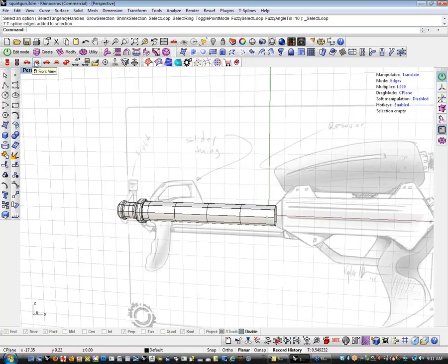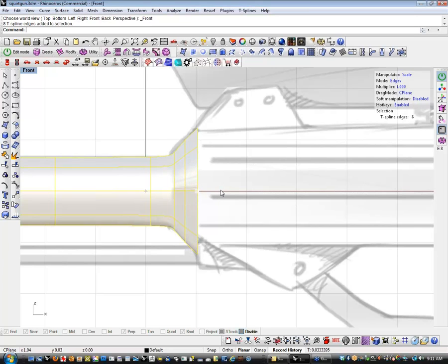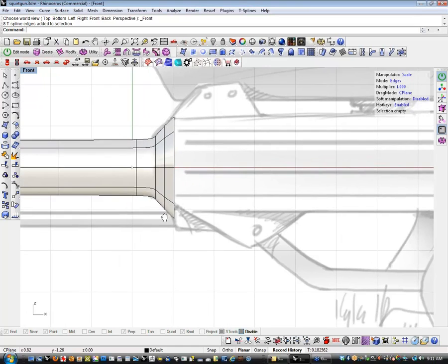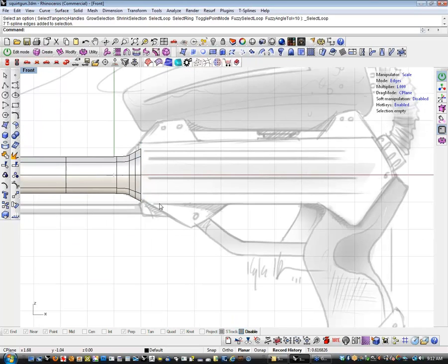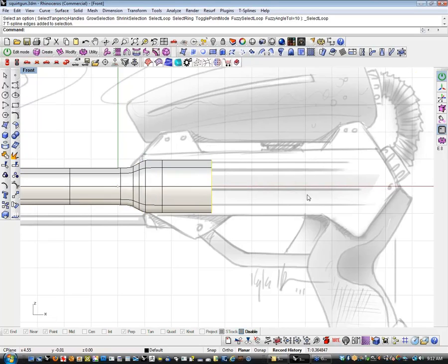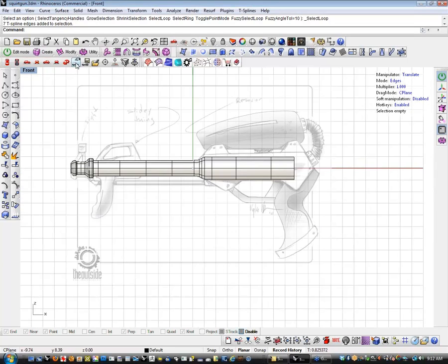Go back here, and I'm going to alt drag out a little bit and scale it to start getting the flare there. Alt drag out again and scale it. And then maybe alt drag out again and scale it one more time. It looks like that's blowing out the constraints of what my original dome was, so maybe I'll shrink these just a little bit. Like that. Shrink that. And then I think I want something that's going to come back in here, so I'm just going to alt drag back in here. I'm going to imagine that this is some kind of tank or something like that.